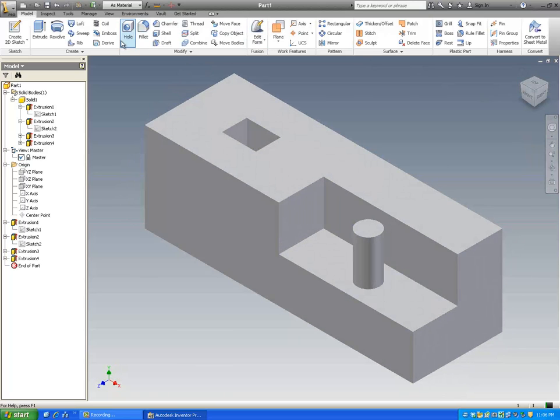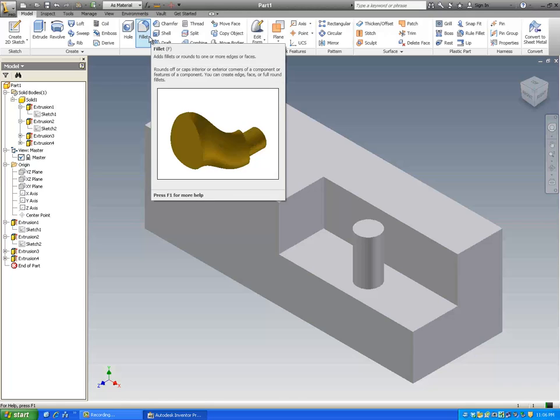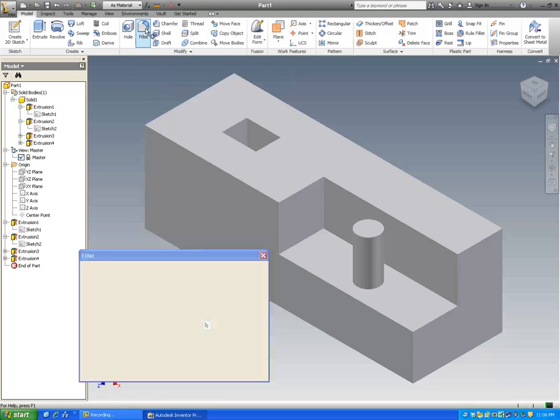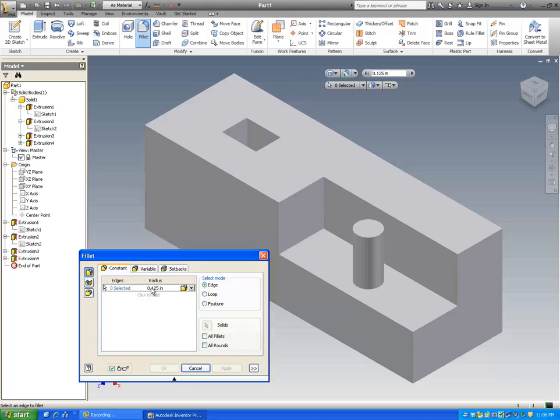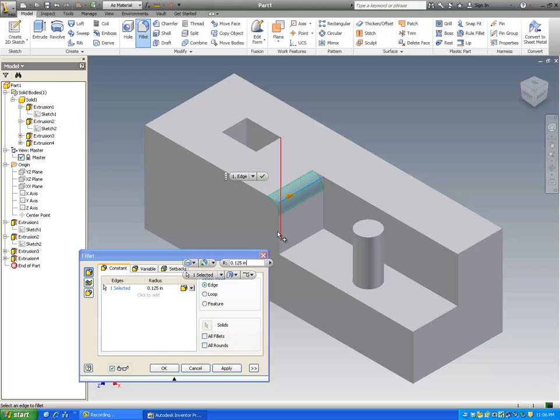When you're in the model tab up here, you've got all these different things you can fiddle with. Okay, I don't have time to show you all of this right now. It's fairly intuitive, but let's say I want a fillet, so I could set the radius of my fillets. I can do all of that. I'll just go with the default, 1/8 of an inch. So I'm going to set those. Those are okay size fillets.